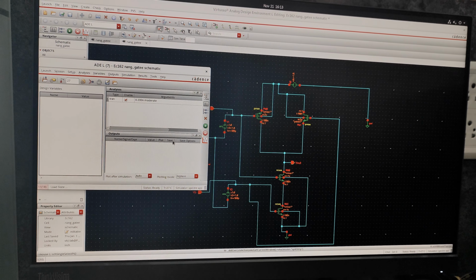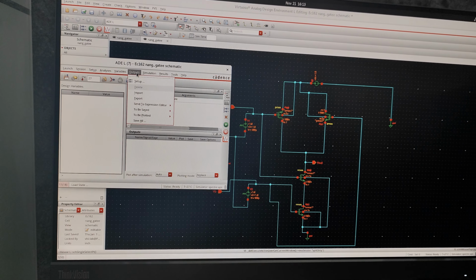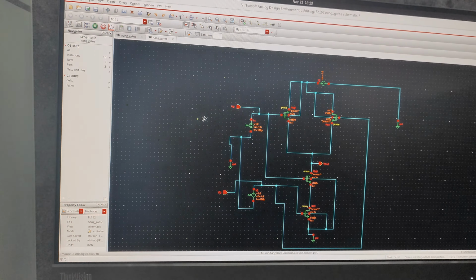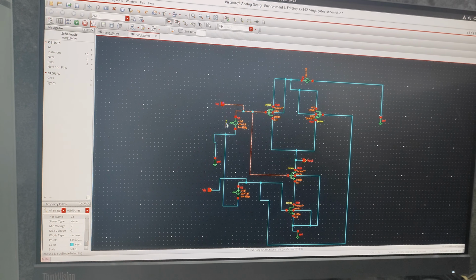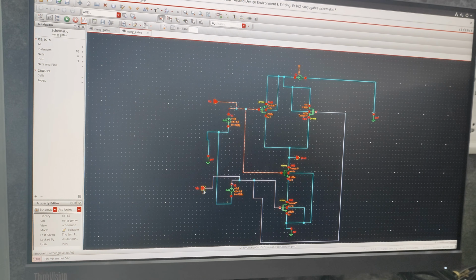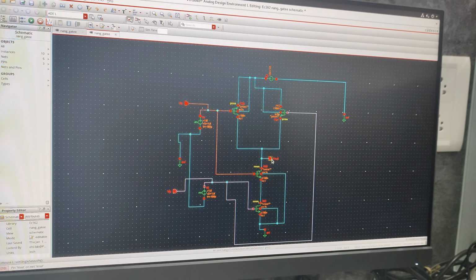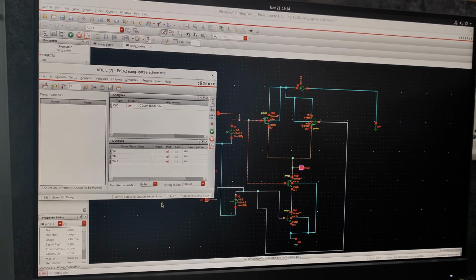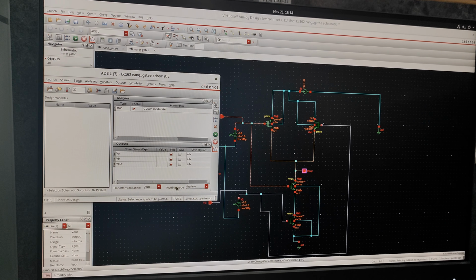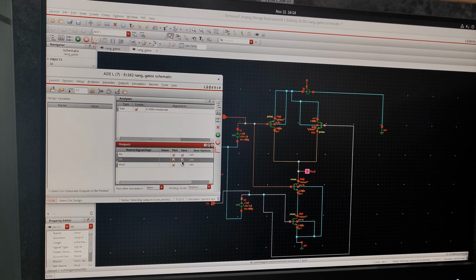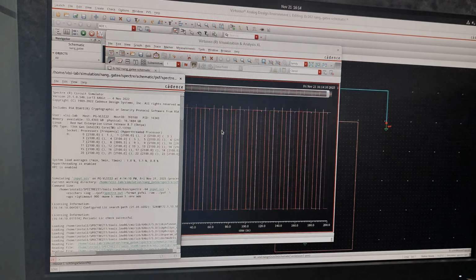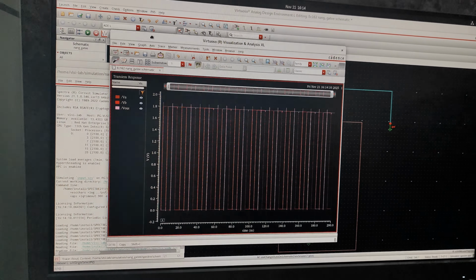then after that click on apply, then click OK. After this you have to go to outputs, to be plotted, select on design, select VA as the input, VB as the other input, and V out, which is our output. Then go to activities, come to the same schematic pop-up box, tick mark the save button, then click on this play button. You'll be getting the schematic waveform.